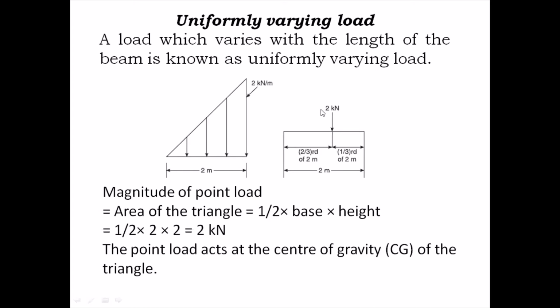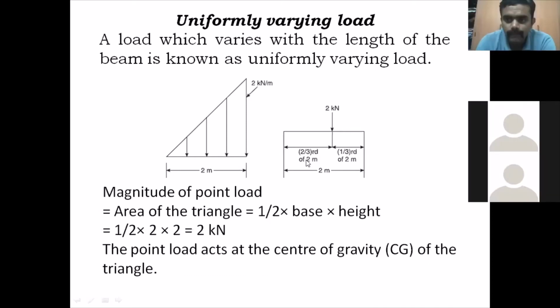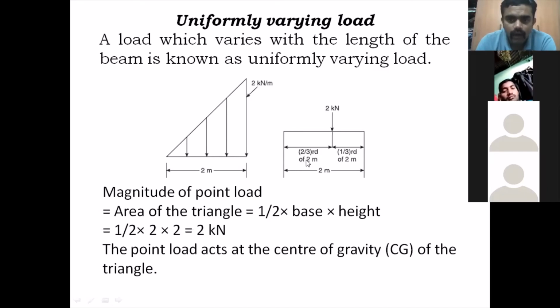So this 2 kilonewton acts at two-third of 2 meter from the apex, or one-third of this 2 meter from the base.